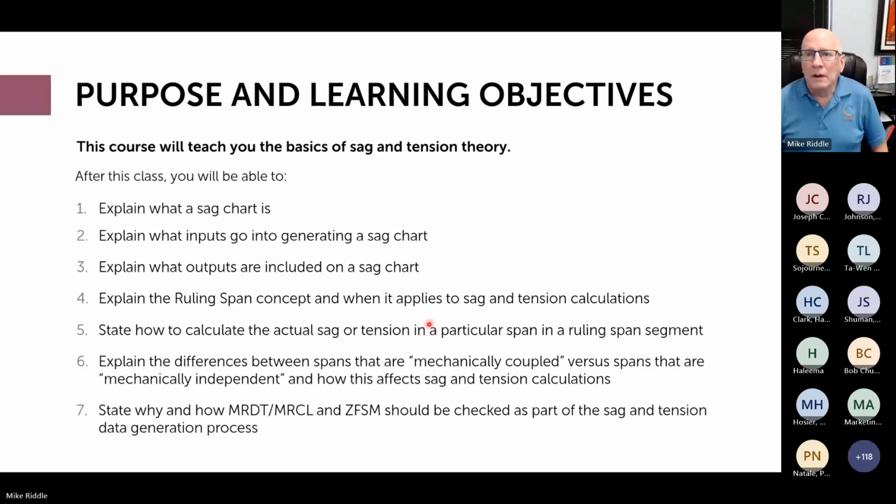So today's purpose and learning objectives. We're going to talk about what a sag chart is, what inputs go into generating a sag chart, and what outputs are included in a sag chart. We're going to talk about the ruling span concept and when it applies and when it doesn't apply. We're going to see how to calculate the actual sag and tension of a specific span in a ruling span segment. Along the way, we're going to learn about the difference between mechanically coupled and mechanically independent spans and how this affects our sag and tension calculations.